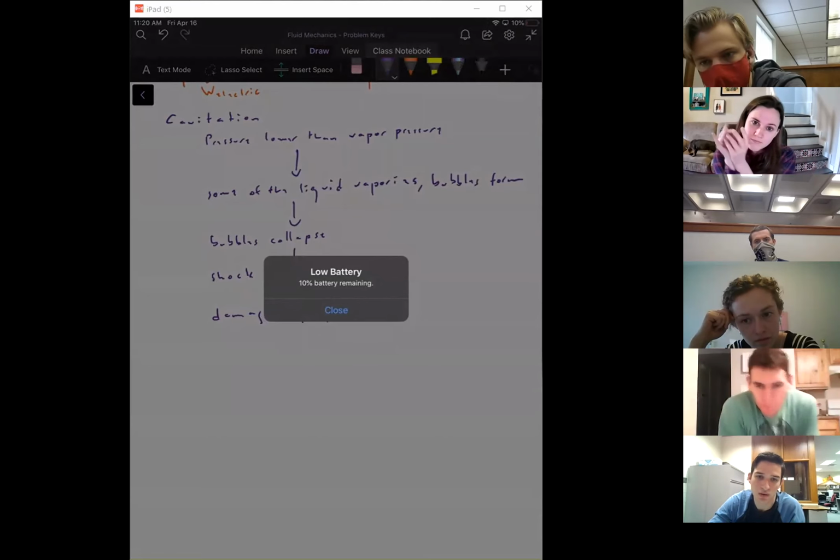Now let's look again at our system. We've got a 0.1 and a 0.2, and this is a pump. Cavitation happens if pressure gets too low, and inside the pump, pressure can also get lower because the liquid is getting swirled around in there. So even if cavitation doesn't happen in the pipe, it can happen inside the pump, and that's bad. We want to prevent cavitation.